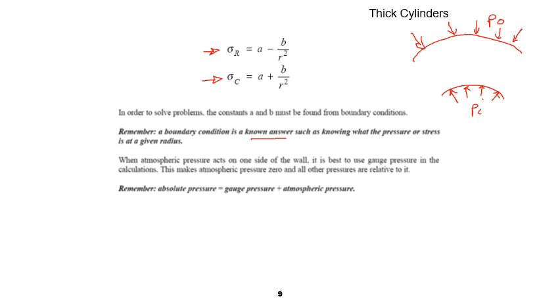In other words, in the material itself, inside, so if we take a stress element there, so remember our sigma r is like that, is going out, but the stress from the pressure is going in, therefore this is equal to negative of the pressure. So if you take a stress element inside, then the radial stress sigma r is minus Pi, right? Is compression.